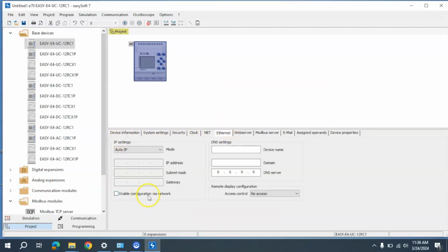Now, if this has been connected to before, all of this information should hopefully be set. If not, there are a number of different ways that needs to be set, giving the PLC its proper IP address and then connecting to the PLC. Ours is set, so we're going to leave that here.